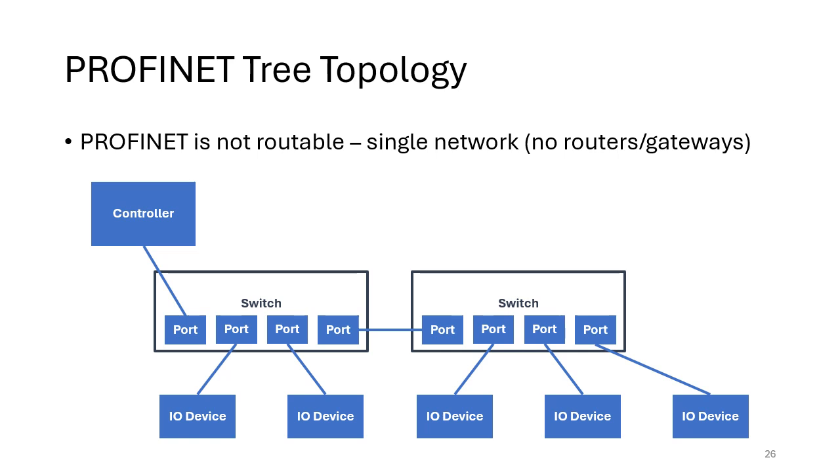The only time this would be an issue is if you were using PROFINET IRT and you really needed that very high speed 31.25 microsecond transfer. So generally, systems like this are very easy to create, and with standard PROFINET with simplex systems without MRP, that can be any switch. It can be a standard switch, managed or unmanaged, layer 2 or 3. It's just a switch. The network doesn't really care.